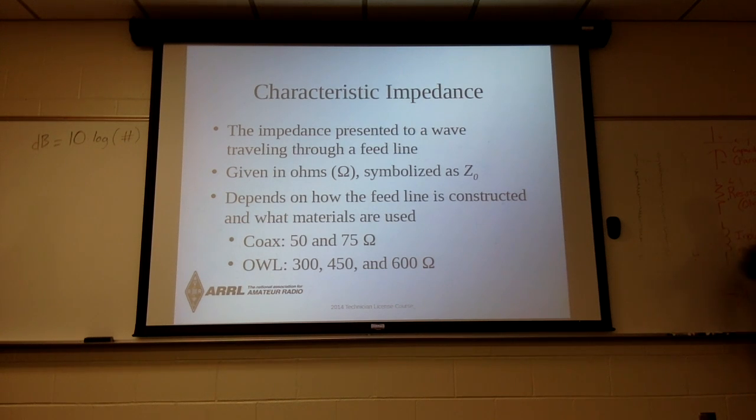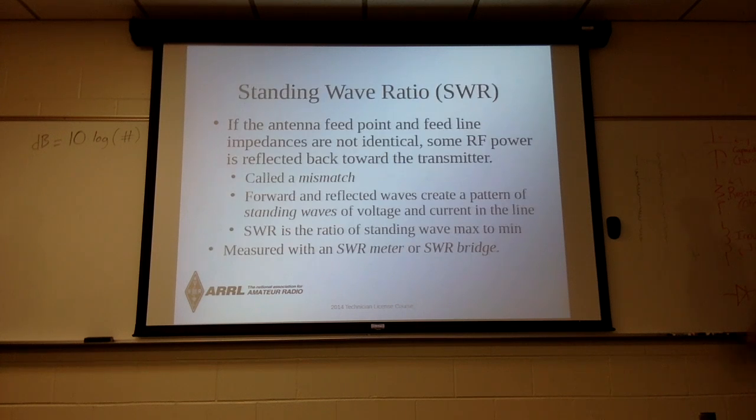You can imagine if you have 2 long wires running close to each other, you have capacitance between the wires. And any wire has inductance, especially if it's really long. So we can basically chop this into little tiny pieces drawn here as inductors and capacitors. And you can definitely learn more about that than we would ever have time for here. But that's kind of how we start looking at what transmission lines do at high frequencies.